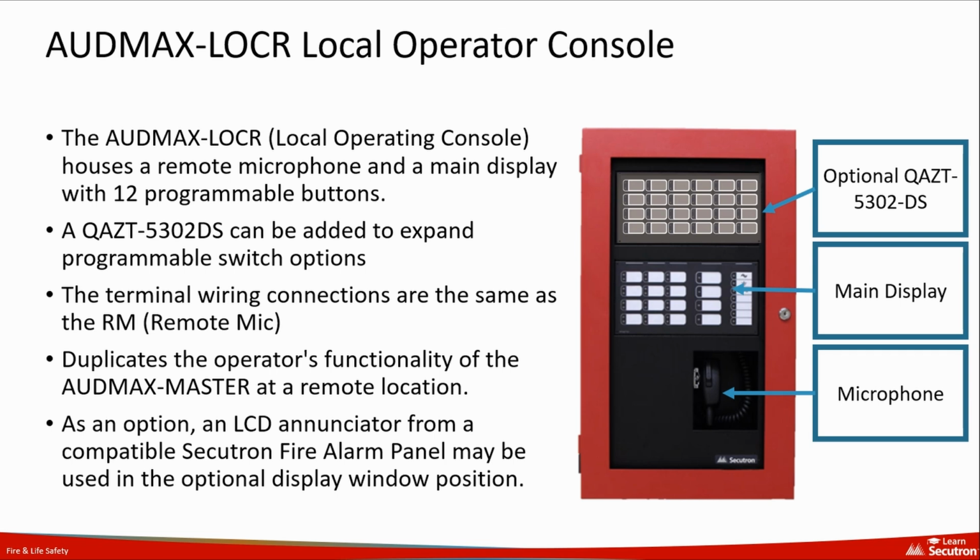Additional space is provided for a 24-button display adder or a remote annunciator display. The connections to the LOCR are the same as the remote mic, 2 shielded twisted pair cables, and 24-volt DC power.